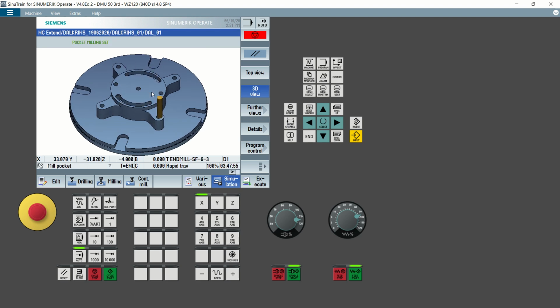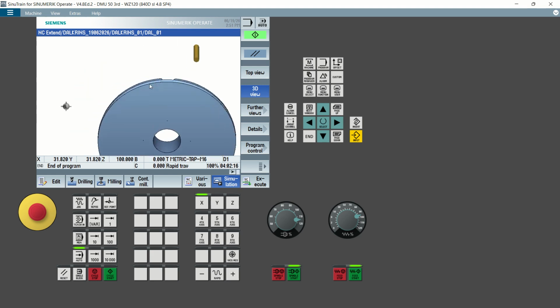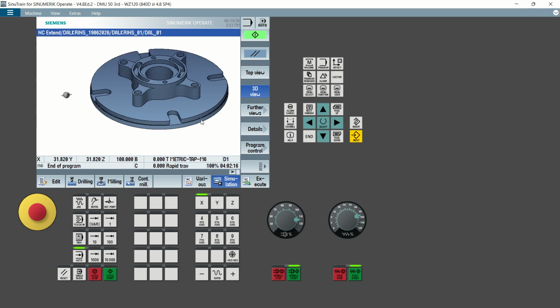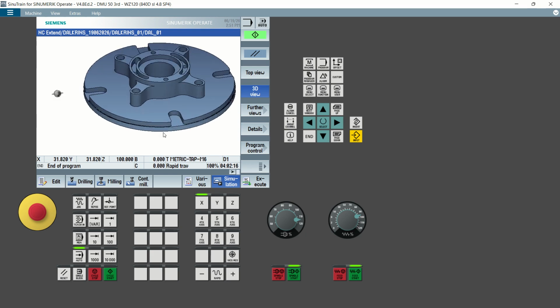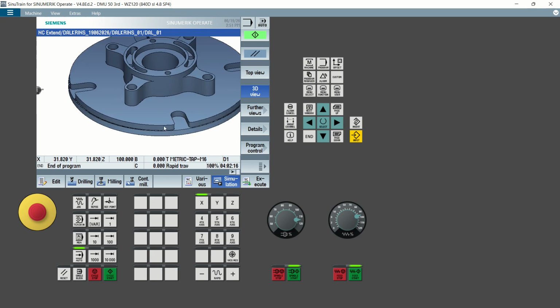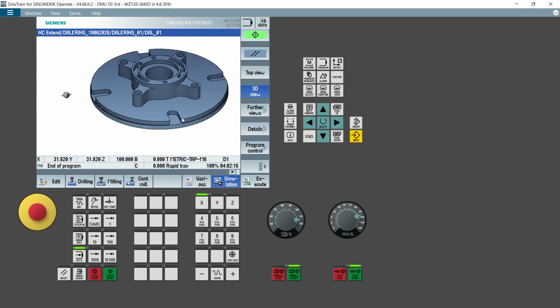This is now milling. All of them have just imported the DXF files. There's nothing I have programmed here from scratch. Just imported the DXF file from SolidWorks. Yes, or from your Inventor, you can do the same. You see? Tapping. And this is what you need. This is the extra material I can turn because it is on the clamp side. Down, I'm clamping on this side. I can now turn the other side and then remove this part so that I can have the finishing part. Let's go to our design from SolidWorks.